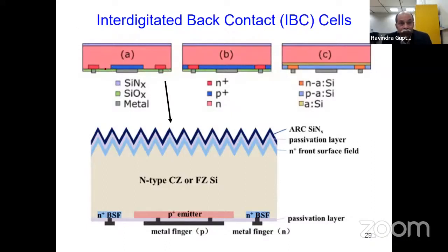And this is the structure you can see here. This is the N-type material, highly doped. This is P-type material, highly doped. Again N-type, like that, it has a series, N, P, like this. And in between, this is the silicon oxide. Then we have the metal grid. And here, this is the P-type amorphous silicon, and this is the N-type amorphous silicon. So we are using amorphous silicon as well as crystalline doped silicon, two things together. So the cost is less, naturally.